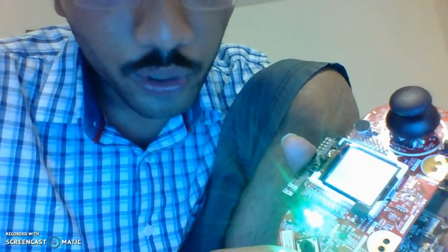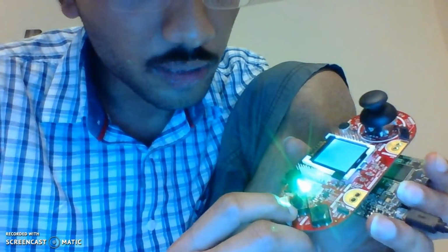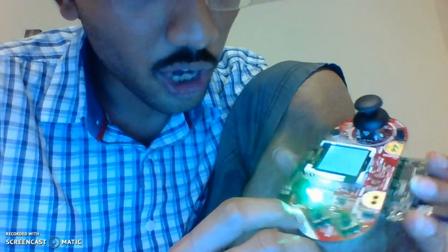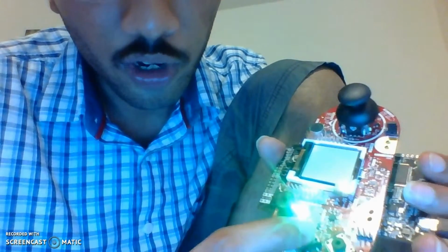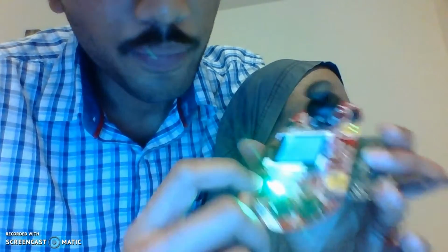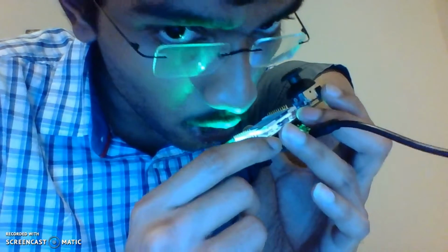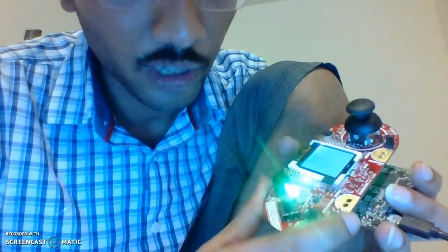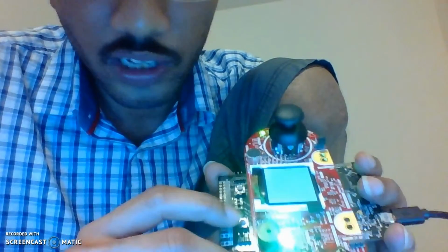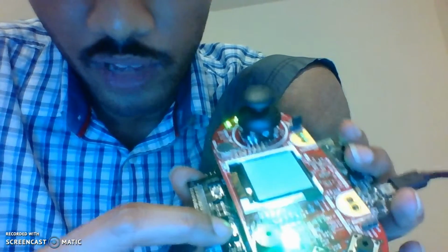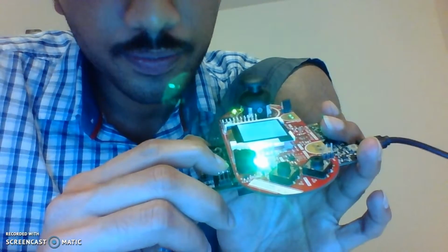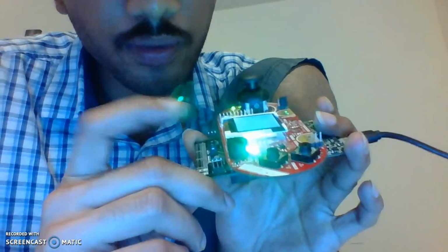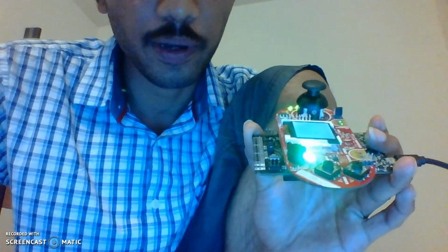Now you hear a fire alarm through the system, and the only way to stop the fire alarm is to press the reset button. Even if you press the doorbell right over here, it's not going to stop. And even if you go and shout near the board, hello, hello, hello, it's not going to give the burglar alarm because the fire alarm is the highest priority. And the only way to stop it is to press the reset button. So the S2 button of the MSP432 board. So let's go and press the button. Yes, now it has stopped the fire alarm.